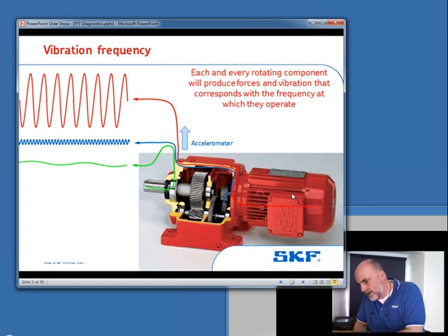And there's a word that when I had a full head of hair and I started hearing people talking about subsynchronous vibration, what does that mean? It just means that we've got sound or vibration at less than the running speed of our prime mover, our electric motor. And rolling element bearings are a really good source of subsynchronous frequencies.